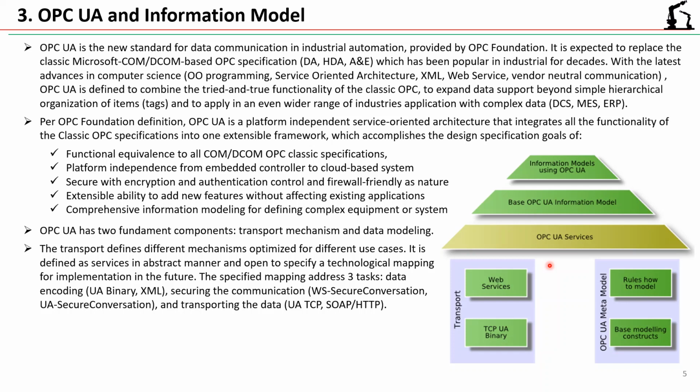With the latest advances in computer technology, like object-oriented programming, XML, web services, and service-oriented architecture, OPC UA is defined to cover not only the well-proven classic OPC functionality, but also to expand data support beyond the simple hierarchical organization of items in the classic OPC specification, and also to apply the usage to an even wider range of industry applications with more complex data, like DCS systems, MES, or ERP.